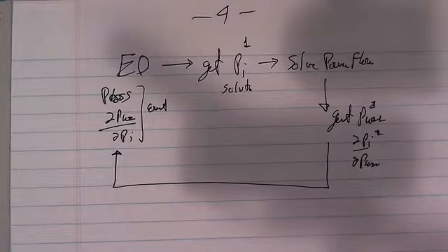And if you're doing economic dispatch on a power system without using a very elaborate optimal power flow, this process is basically the one that you would use. If you're a small regional system and you don't have a lot of transmission problems, this works fine. Okay, so that's transmission losses.